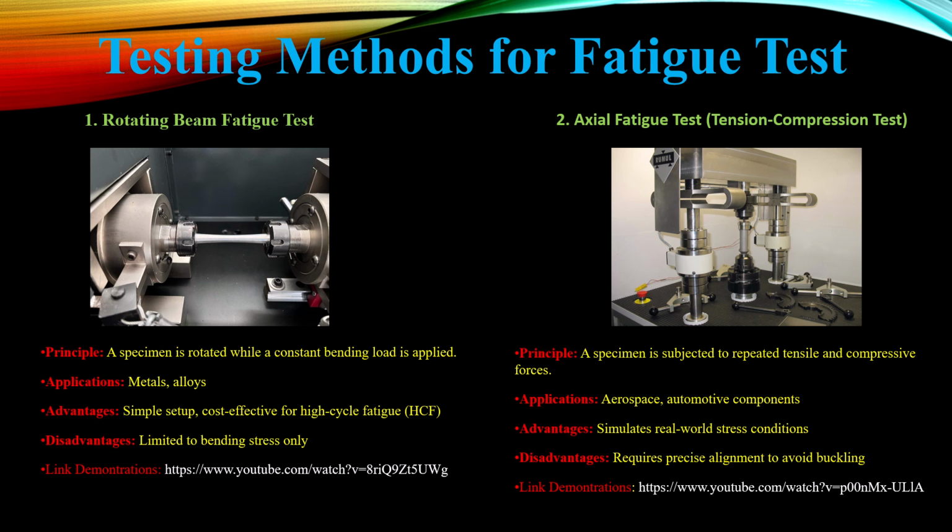Its primary advantage is the ability to accurately simulate actual service stresses, providing highly relevant fatigue data. However, the test requires extremely precise specimen alignment to prevent buckling, which can complicate the setup process and potentially compromise test results.